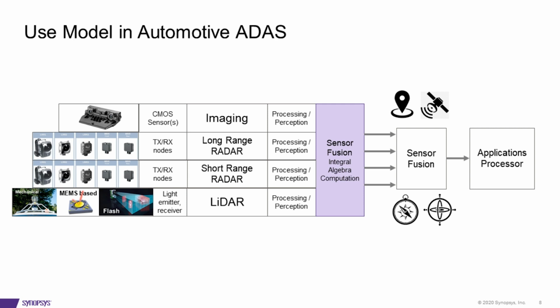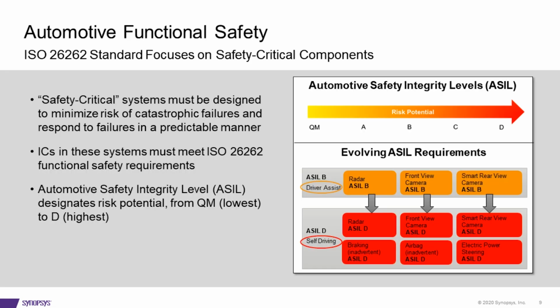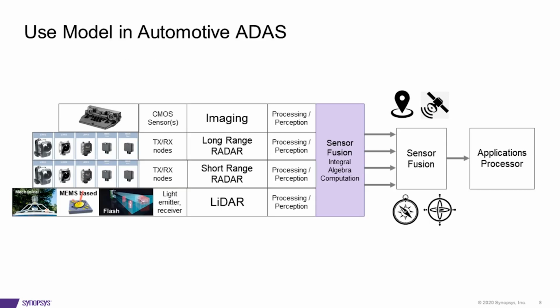And then radar, again, is that echo bouncing off of the object itself, still an important part of the system as well. And that's broken down into short range and long range radar. So all of these technologies are fed together to give an overall picture of what's happening around the vehicle. All of those images and data values have to come together and be fused together, and that generally takes quite a bit of DSP processing to manage.